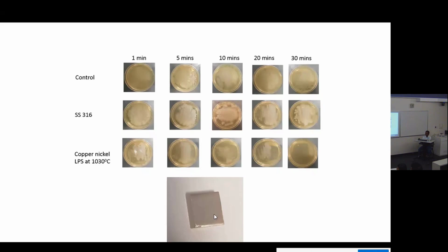How do the properties of the manufactured items differ between additive manufactured and say cast? Things like strength and flexibility and those sorts of things. It won't be very different. In fact, the additive manufactured part using cold spray would be better, because we can add anything that we want to this. There won't be any segregation that can be easily seen. If you make a casting, you will have intermetallic segregation.